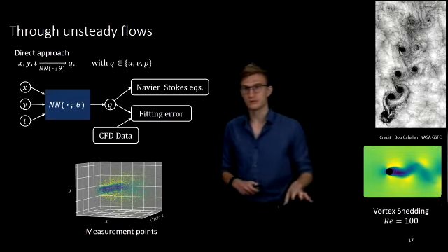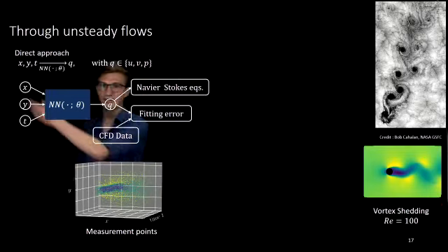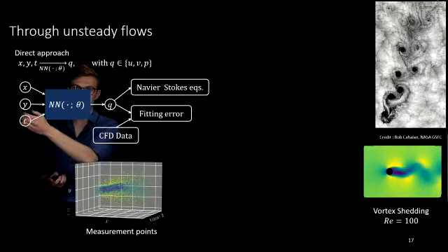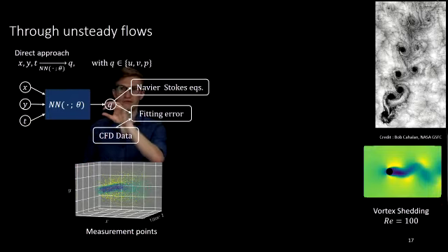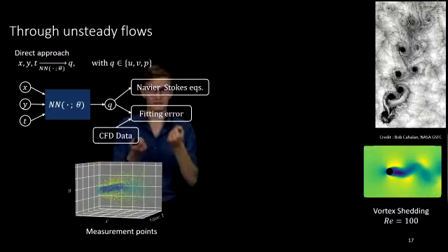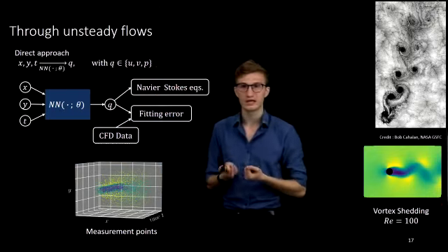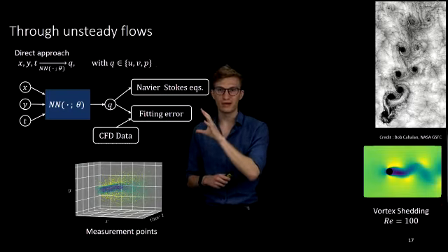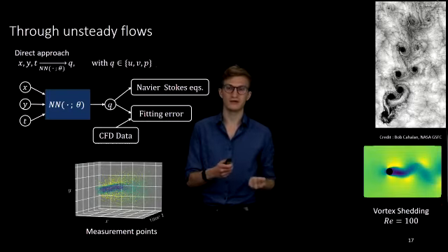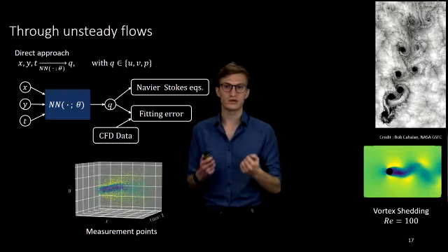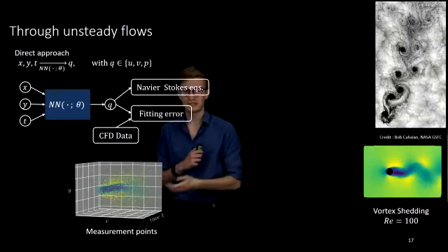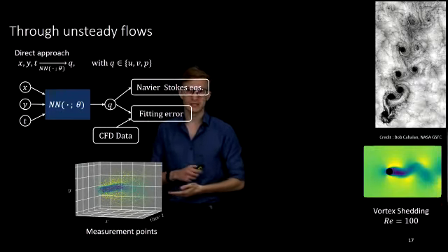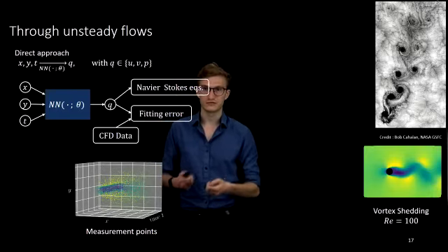And to solve that, we use the PINNs with inputs which are the space x, y, and the t coordinates. These neural networks approximate either u, v, and p, the three components that are unknown, and we train that using the residuals of the Navier-Stokes equations, and also an error based on data. And this time we don't have exact data, and we don't have boundary conditions. So we sampled data from simulations provided by Mohamed Boudina in the CADYF code.